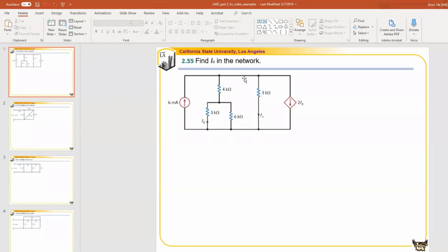If I look at this whole problem together, I already have two currents that I don't know. If you want to use KCL, like what we did last week, you can potentially use KCL to find the equation. For this circuit, we have one node here, one node down here, so we can pick one node to write the node equation. Then we'll be able to find a relationship between Io and Ix. On top of that, we can try to find a relationship between this current and this current by looking at their resistance relationships. All right, let's do that.